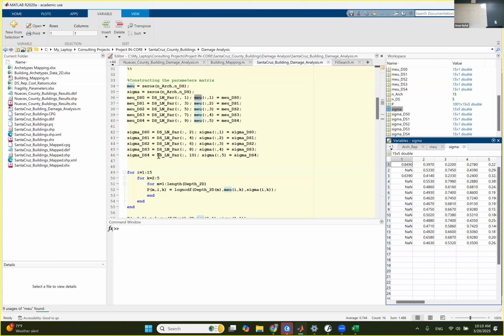For depth equal to 0.01, 1 centimeter, try to find the exceedance probability, or the value in the CDF, given the values of lambda and XC, because lambda and XC help you draw the curve. So we draw the curve, and then take the flood depth and calculate the value on the y-axis, and he puts it in this matrix.